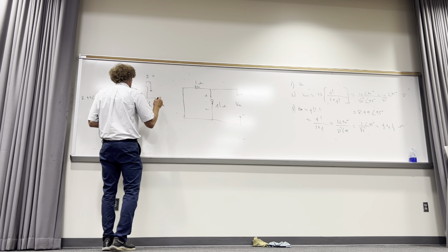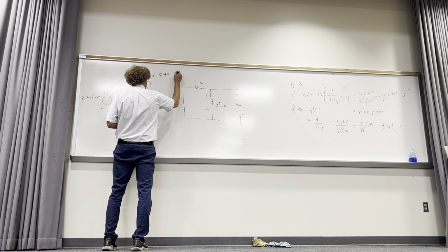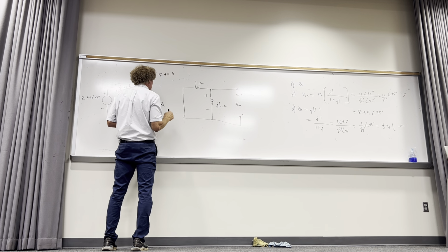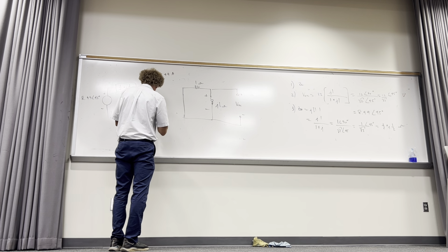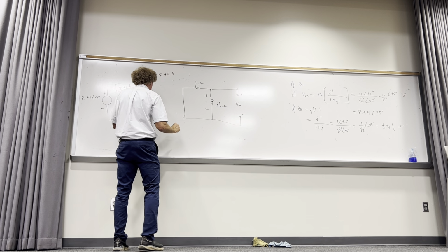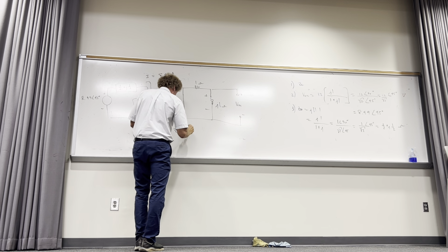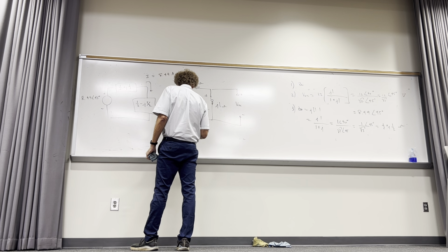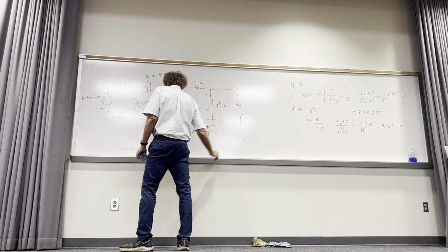So it's just going to be equal to 8.49 amps, and I don't really care about the angle because the power absorbed is really the power absorbed by the 1/2 ohm. That would be 8.49 squared, magnitude of current squared, times the resistance 1/2. So I need this one value and square it, divided by 4. What do we get for that, class?